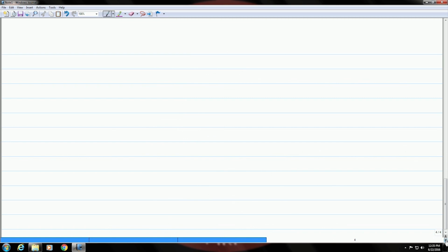Then if there are brittle inclusions or some kind of impurity leading to the formation of brittle foreign elements inside a metal, then fracture of these brittle inclusions when you apply the load can also generate acoustic emission.